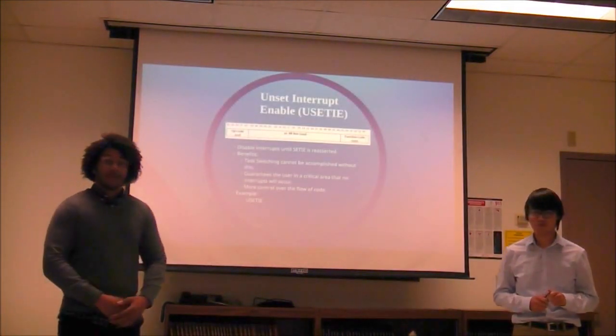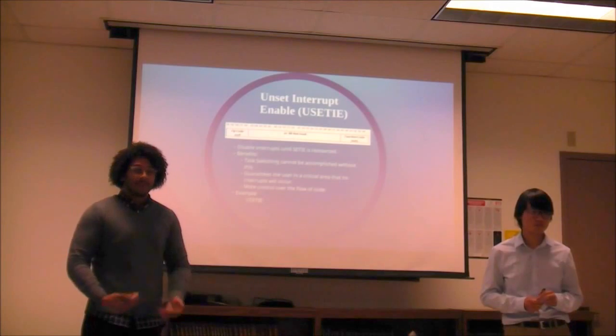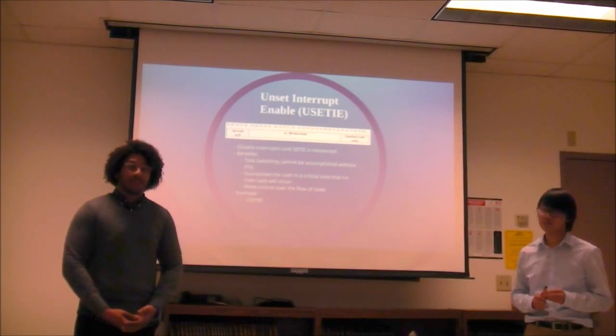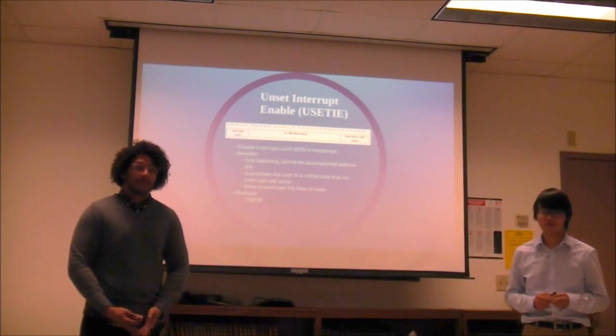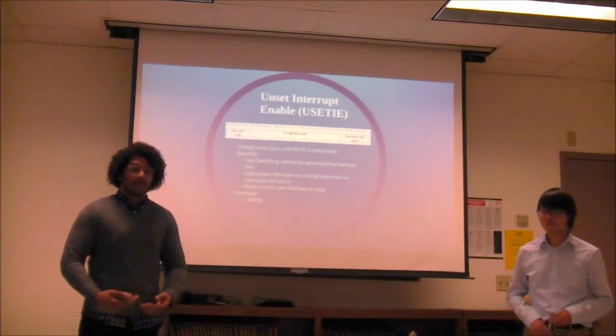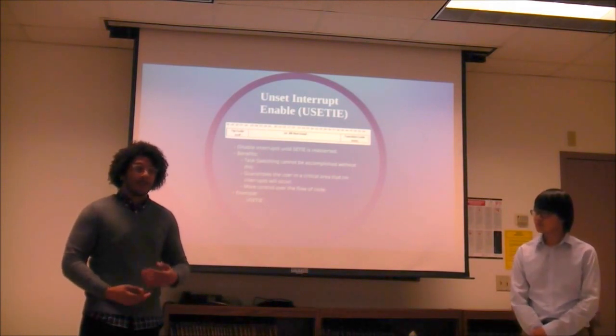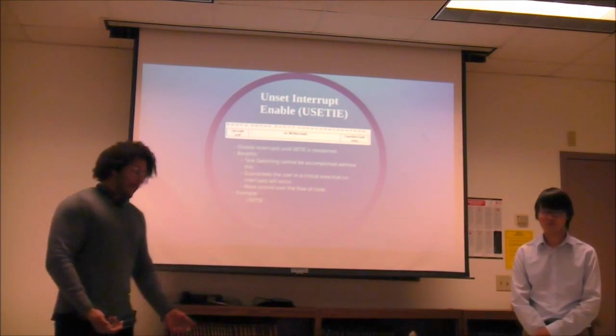As well, you have an unset interrupt enable. If you have a set interrupt enable, I just felt it was necessary to have an unset interrupt enable, to make sure that when you're in certain critical areas, you don't have another interrupt occur.